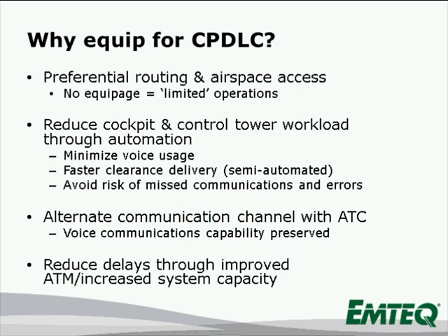There are several benefits to equipping for CPDLC, and there's a strong motive from the air navigation service providers. Really what it comes down to is air traffic management, a means of sticking more aircraft in the same airspace. It allows reduced lateral and longitudinal separation in conjunction with ADS-B, which is also due to be implemented later in this decade. For aircraft that are equipped with CPDLC, what it will allow you to do is to pick up preferential routing.